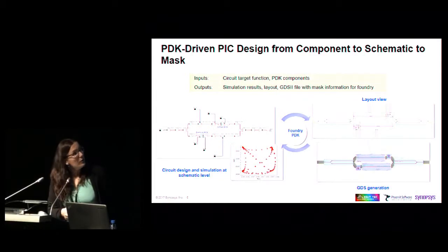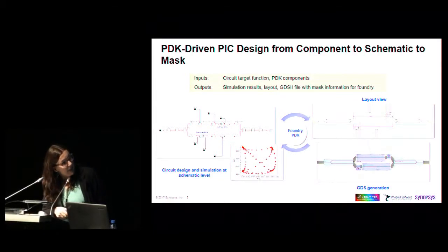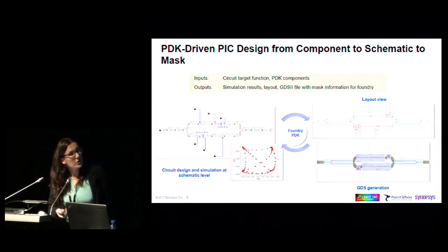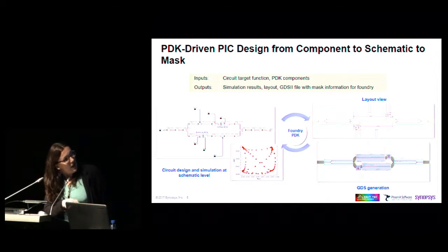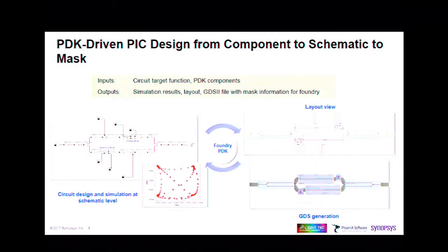Then, when you have this PDK model, you will design your PIC. From the initial idea concept that you have in mind, you will test at the schematic level the physical behavior of your PIC. If the simulation results look like what you are expecting, you will go from the schematic level to the layout level.